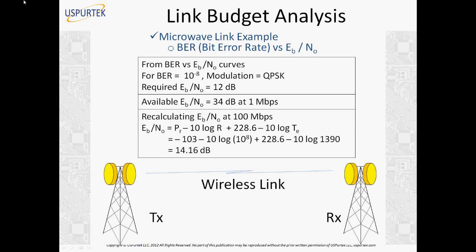Well, somebody commented, isn't that contrary? Well, here we are talking about data rate. We are not talking about frequency here, or the available bandwidth and whatever data rate we can transmit. So what we are trying to emphasize here is that there is a limit to how much data you can transmit at a given Eb/N0 or at a given signal to noise ratio per bit. So we have a different focus here. We're just trying to determine what is the limit to our data transfer rate for a given Eb/N0, right? So this formula will help you determine that.